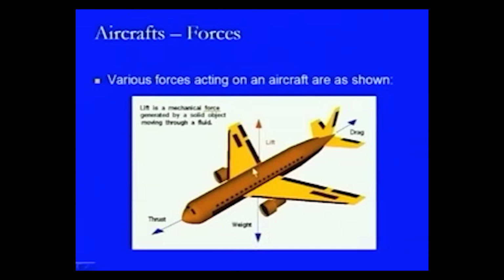Then there is another force acting in this direction, which is basically a propulsive force generated due to the thrust generated at the back if it is a jet engine, or otherwise if it is a propeller engine, then it is sucking the air on this side and pushing the aircraft in the forward direction. So, that is why there is a thrust with which this aircraft keeps on moving in the forward direction. This is acting in the x axis direction longitudinally.